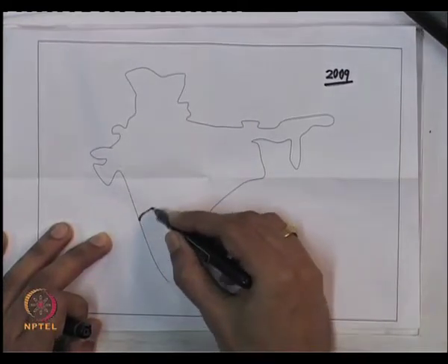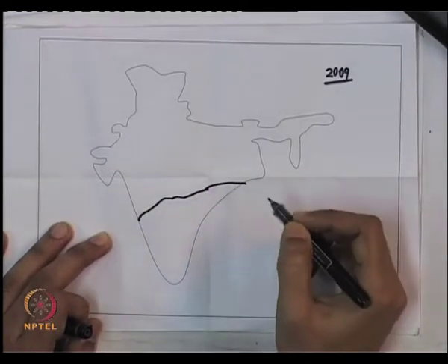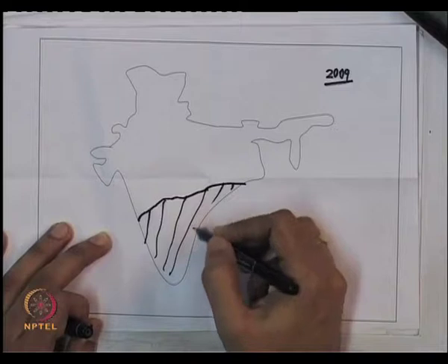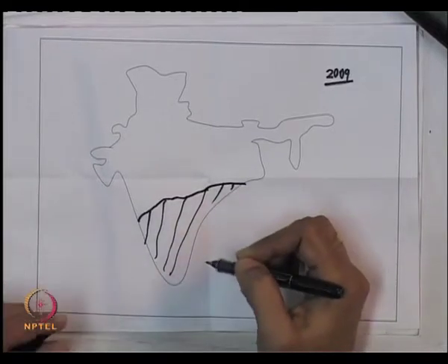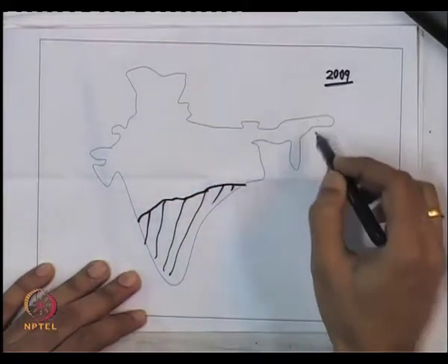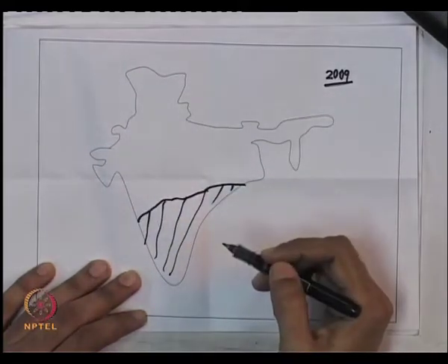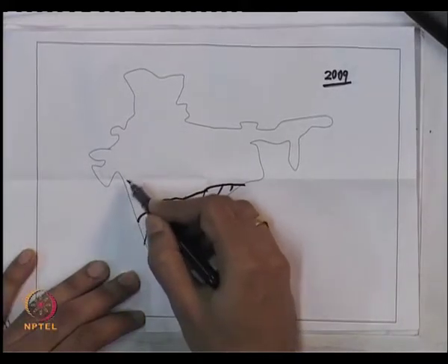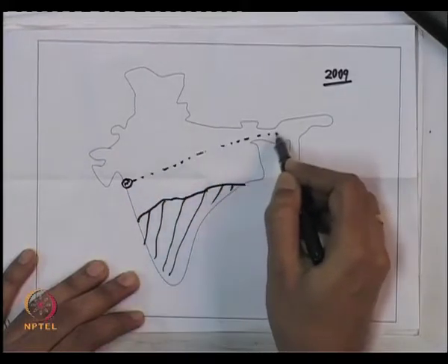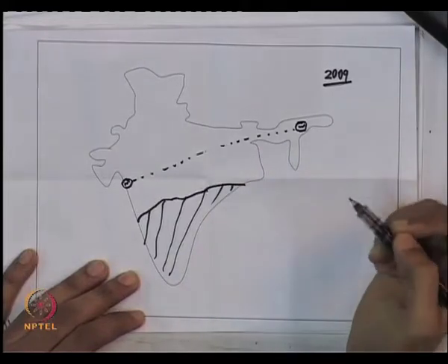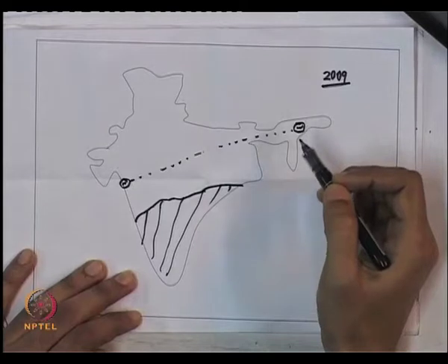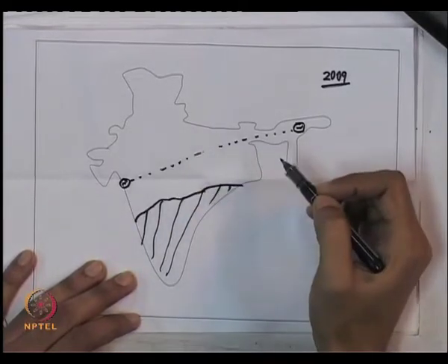The southern part of the peninsula forms one synchronous grid, that is, the synchronous generators in this part of the system are interconnected to each other by AC lines. The second synchronous grid in India is the rest of the system. The rest of the country is actually another synchronous grid. So, if you start off with one generator here, say at Trombay, and you follow the AC line paths, you can go to another generator in the same synchronous grid through only AC line paths. So, all the generators in this northern part of the grid are actually in synchronism in steady state. So, they run at the same electrical speed in steady state.